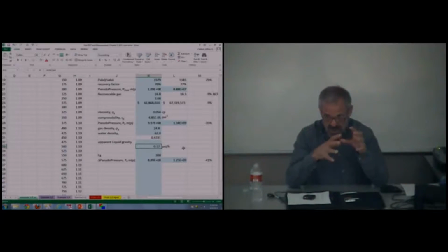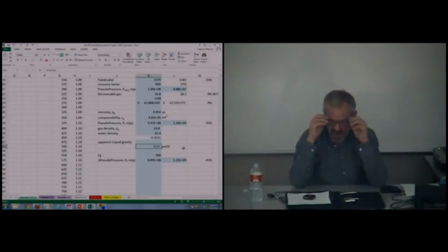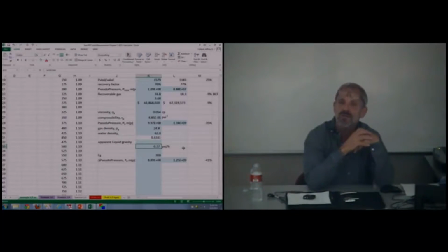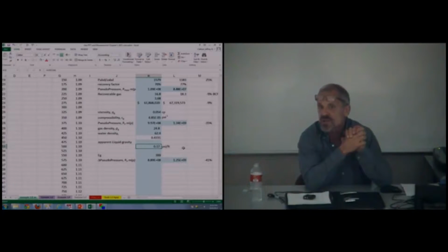Frequently, there are ways to make deterministic solutions moving forward. But we can really utilize a lot of these gas PVT and gas utility functions for modeling, like we did in the first problem we did in class, where we had to figure out the gas gravity, looking at the experimental results that would give us Z factors as a function of pressure.